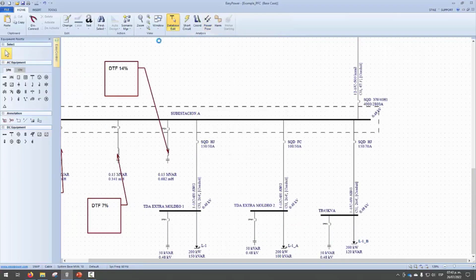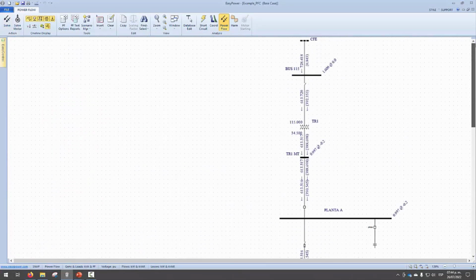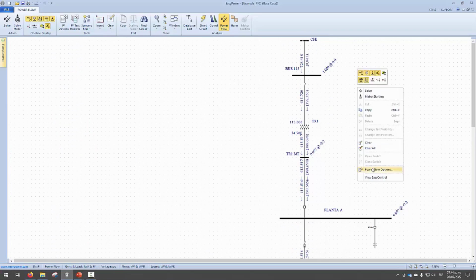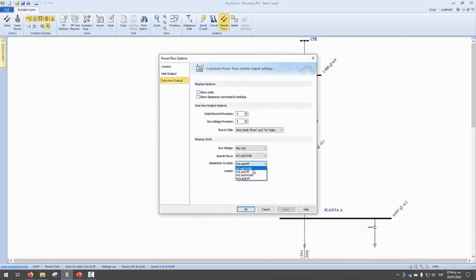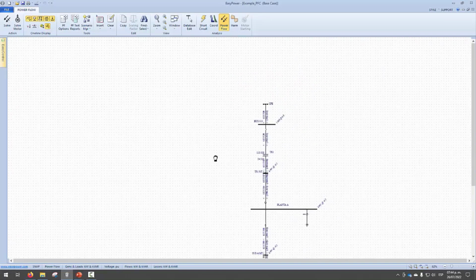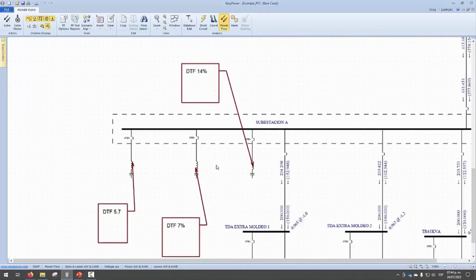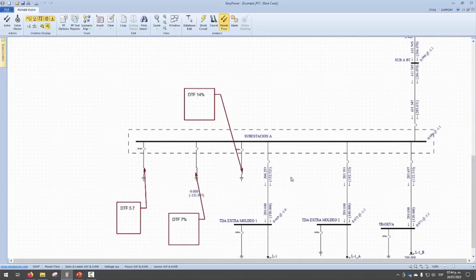So I'm here at the beginning, and then I need 382 kVAR. So then I decide to implement my solution at the substation level. And I'm going to do it with capacitors, but they're going to be detuned banks. So I'm going to go with the most common, let's say it's 7%. And this one provides 130 kVAR.